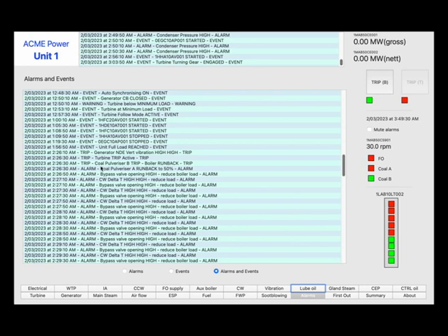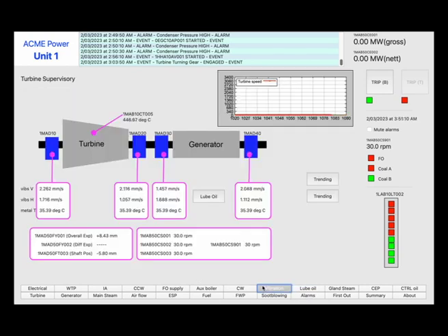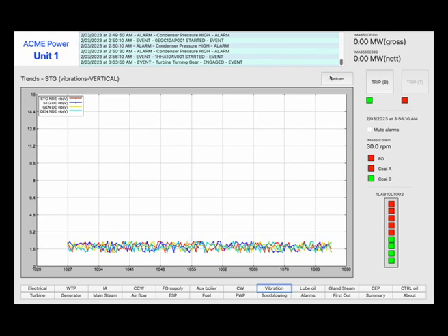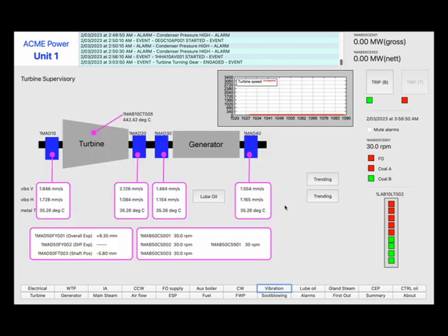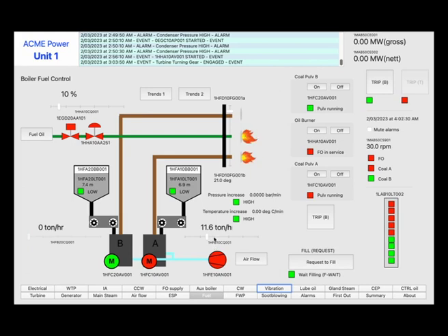After investigation by the maintenance staff, it has been determined that this high vibration level was caused by a loose wire and has now been corrected. You are safe to go ahead and resynchronize the generator to the grid. Increase pulverizer coal flow controller to 18 tons per hour. The extra heat of this coal is required to increase superheater outlet temperature to meet the requirements of a hot start-up.